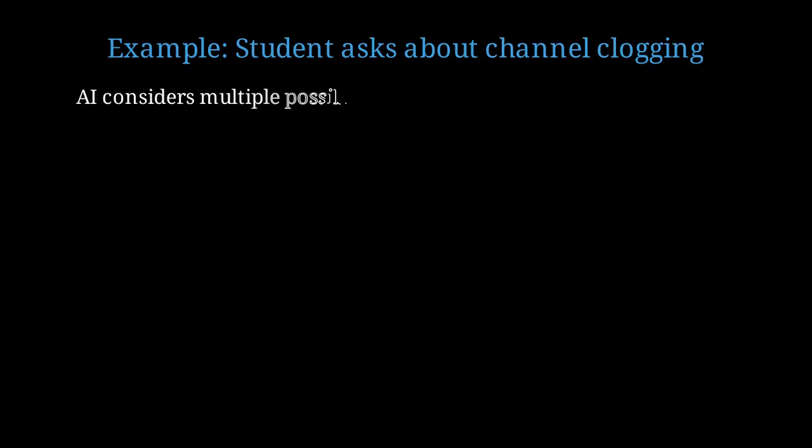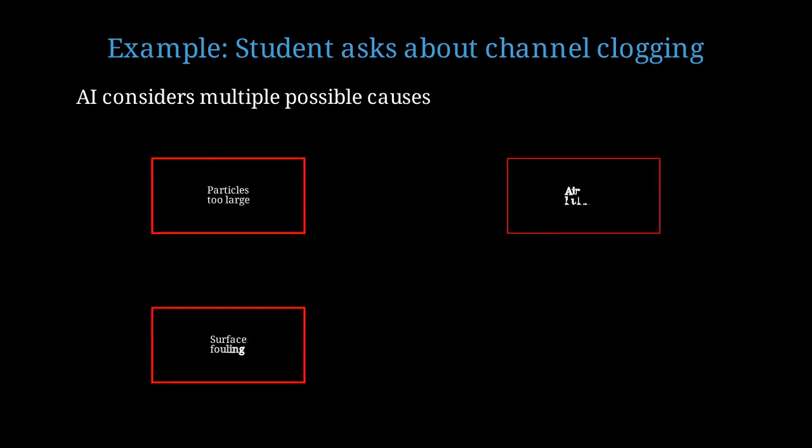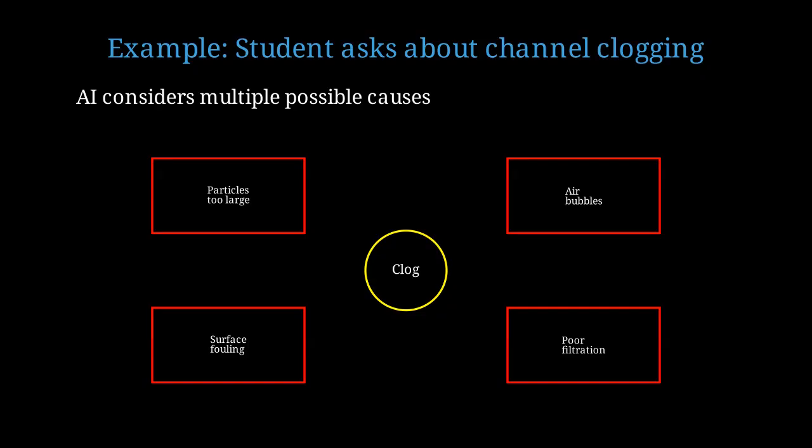The AI considers multiple possible causes: particle size relative to channel dimensions, surface chemistry and protein absorption, air bubble formation, inadequate filtering of samples, or fabrication defects. It then asks targeted diagnostic questions to narrow down the actual cause. What's your channel width? What's the particle size distribution of your sample? Are you using filtered solutions? This mimics how an experienced professor would troubleshoot.